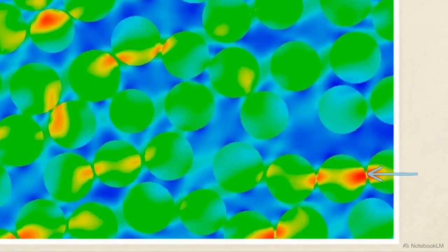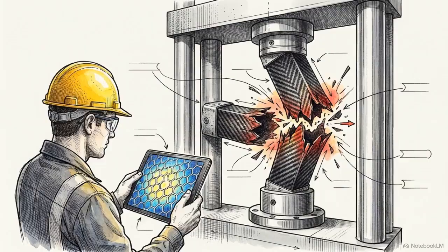In reality, physical stress pools heavily around these manufacturing defects. During loading, extreme stress spikes localize precisely at the points of fiber agglomeration. Evaluating a composite based on a uniform grid blinds engineers to these localized stress spikes, causing them to overestimate the structural strength of the material.